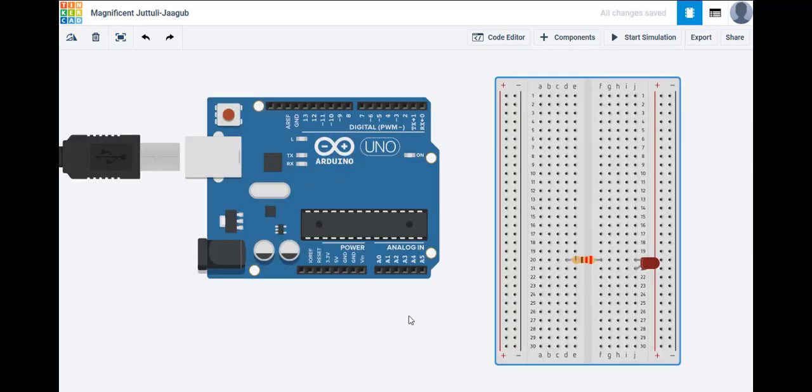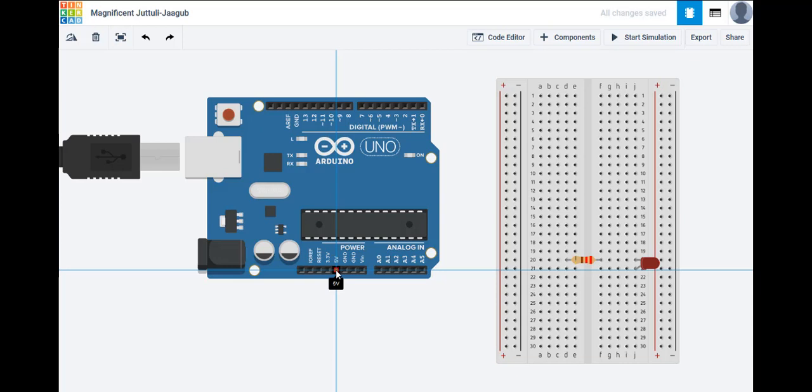in the view. Now, these power rails, positive and negative, are used to share out a supply such as this 5 volts between multiple components in a more complicated circuit than the one we've got here. So if I take the 5 volts, click there, drag a wire down to here, the blue lines will appear above and below to help you keep it vertical or horizontal, which keeps the circuit easy to follow when in a more complex circuit.